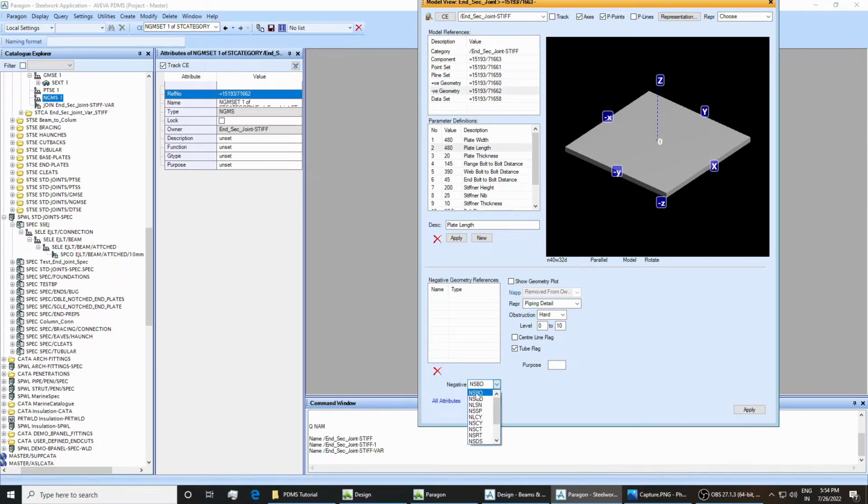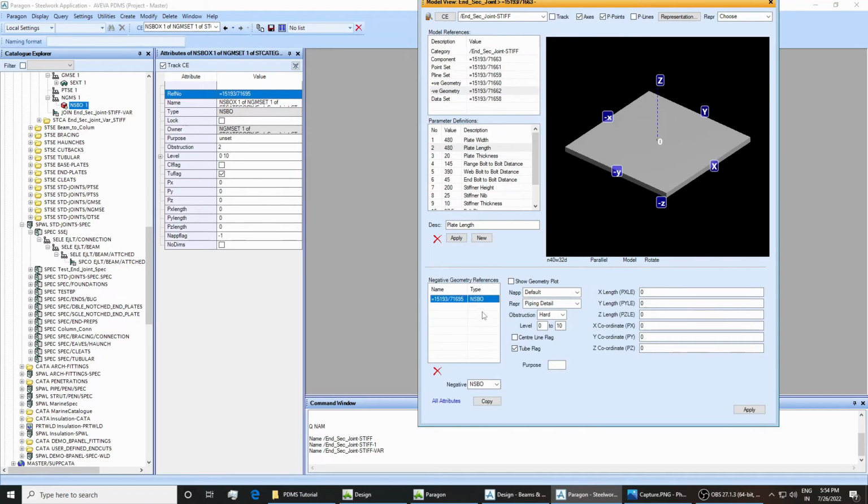First of all, here we will create one negative solid box, and we have to define the x length and y length. So what will be the x length and y length? We will write here a par 1, and here a par 2. What is a par 1 and what is a par 2? I will definitely tell you; first let me define it, then I will tell. And here we will write RPRO PTHK, I guess that is the plate thickness. Now click on apply.